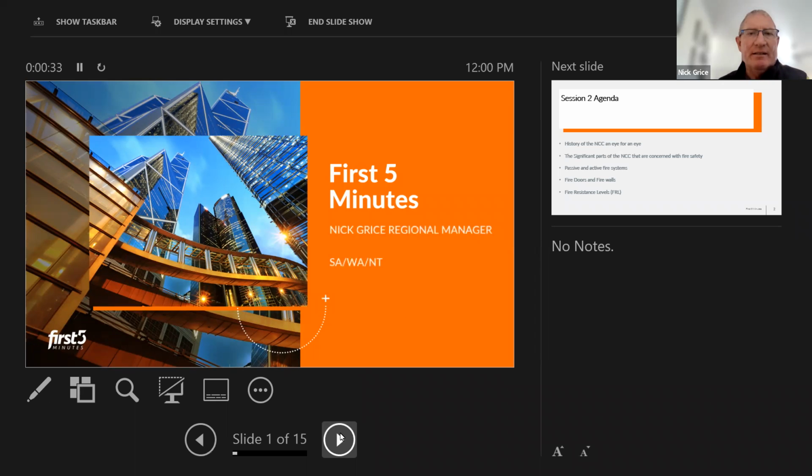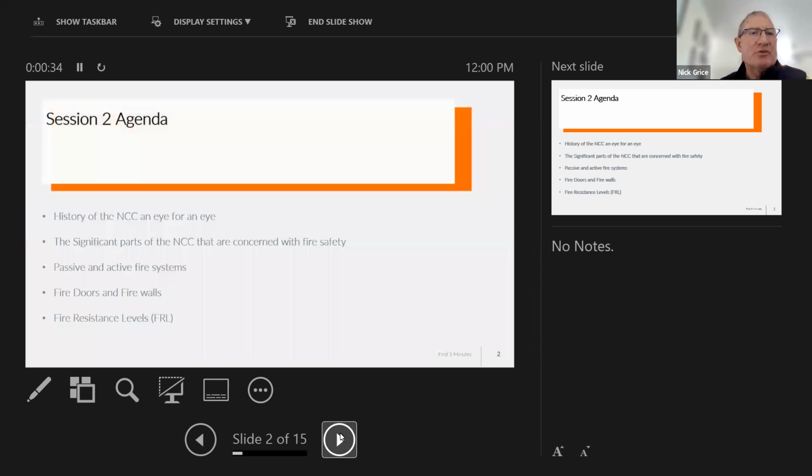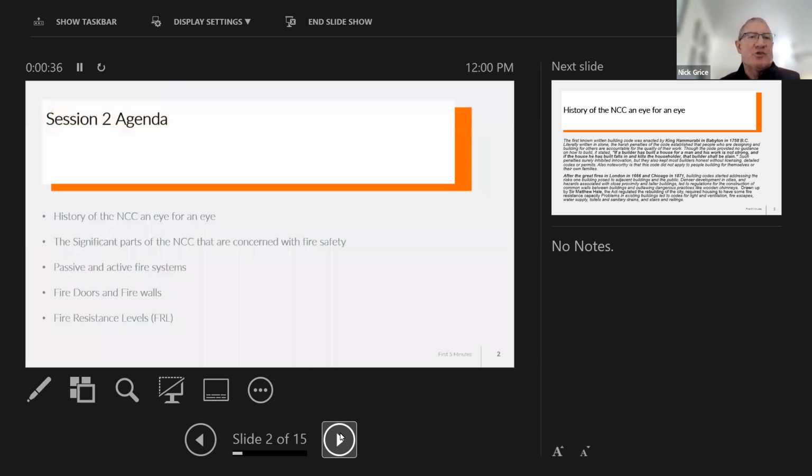Today we're going to talk to you about the history of the National Construction Code, formerly the Building Code of Australia, and an eye for an eye. The significant parts of the National Construction Code that we're concerned with are fire safety. We're going to have a look at passive and active systems, which there are loads of in buildings. We're going to talk about fire doors and firewalls, and talk you through fire resistance levels, which is quite important